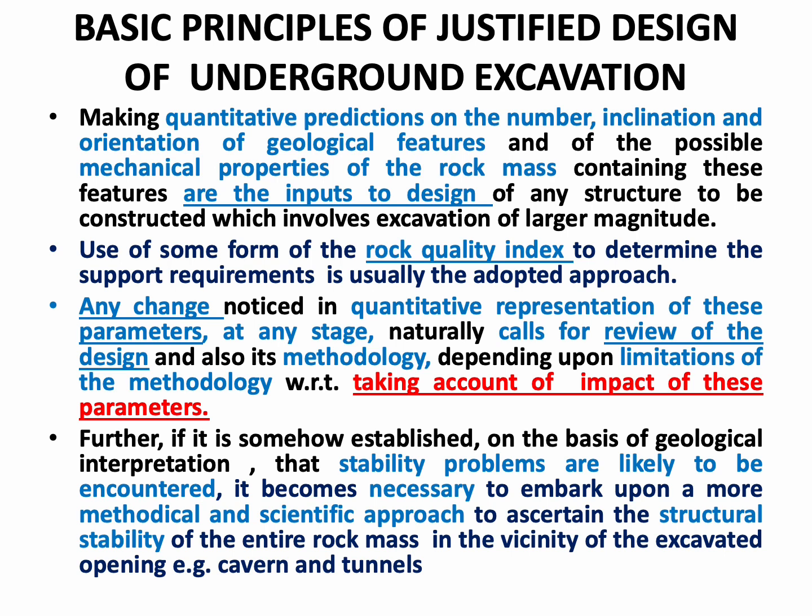Use of some form of the rock quality index to determine the support requirements is usually the adopted approach. Any change noticed in quantitative representation of these parameters at any stage naturally calls for review of the design and also its methodology, depending upon the limitations of the methodology, taking account of the impact of these parameters. So to start with, a rock quality index is the parameter which determines the support requirements, and at various stages of the excavation,